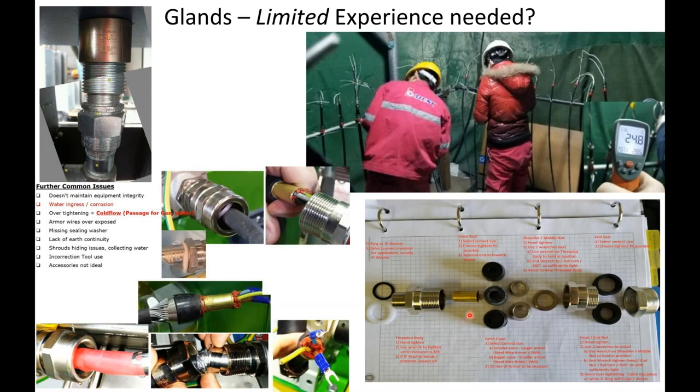So what can we do? Well, here's an example of too much complication. This would come in a bag. So people would install an O-ring and an IP washer. 100% failure, one would have to be removed. So the amount of man hours spent on reworks is maddening.